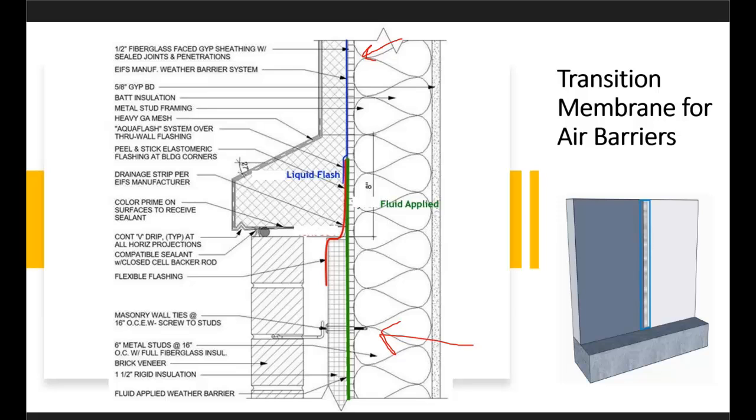I do want to mention that the self-adhering stainless steel is a certified air barrier. It's a certified air barrier as a product. It's not part of a system. It doesn't need to be if it's just a transition here, per ASTM E2178, so there's no hesitation using it as part of your air barrier system to make it continuous. Not to mention, it has a lifelong performance.